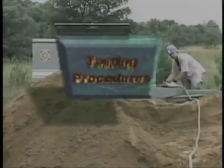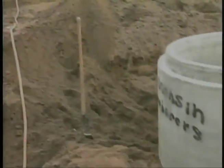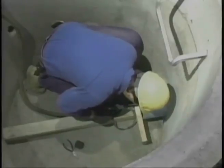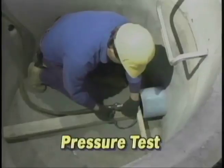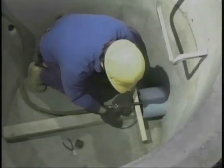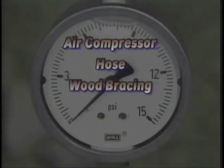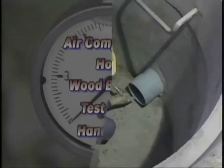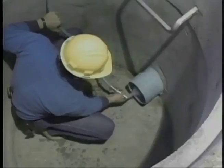In some circumstances, a contractor or project owner may be required to have an independent agent perform a test on a completed sanitary sewer installation. Most testing specifications require a pressure test. A low-pressure test is performed on an isolated section of pipe. This test requires an air compressor, hose, wood bracing, test plugs, and a hand pump. Pre-test flushing of the line removes debris and can improve the overall test results.